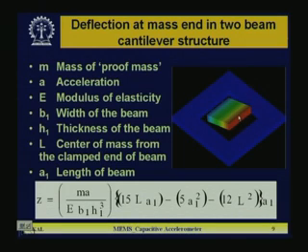So whatever movement there is will be along the z direction, either upward or downward. If you move it along this direction, it will not show any upward or downward shape change. Because of that, you can reduce the cross axis sensitivity problem.